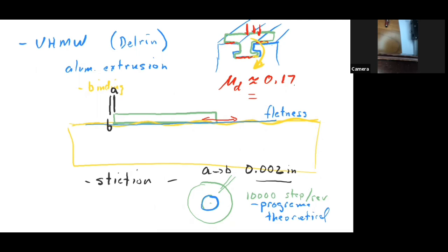If we had better gauges, if we put an encoder on it, or maybe you even put a laser pointer on the shaft, and I've done this before, and then you point the laser pointer at the wall, 20 feet away. And then you do 1 microstep of this motor, and this doesn't move. 2, 3, 4, finally, it moves up to this spot. And that then is, this was theoretical, the smallest, your resolution.